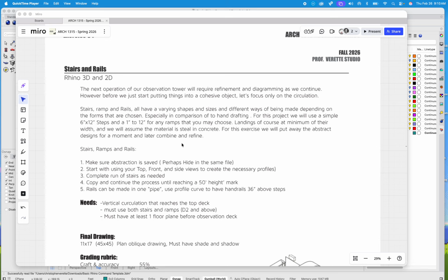So we do start to get a little bit more architectural, and the best way that I can explain that, guys, is, well, if you have ramps or stairs, and it's a certain thickness, let's say it's 3 feet. And you'll definitely learn this later, and you'll probably even see it in the architecture that you go through, but if this is a width of 3, or 4, or 5, the landing itself, by minimum, has to be that as well. Does that make sense? That also has to be at least 3.